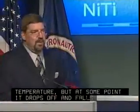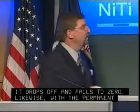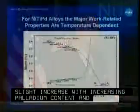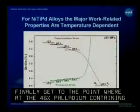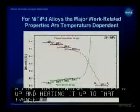Likewise, with the permanent or irrecoverable strain, there's a slight increase with increasing palladium content. And again, you finally get to the point where at the 46% palladium containing alloy, just loading the material up and heating it up to that transformation temperature causes the material to fail. So if you want, go to the next slide, please.